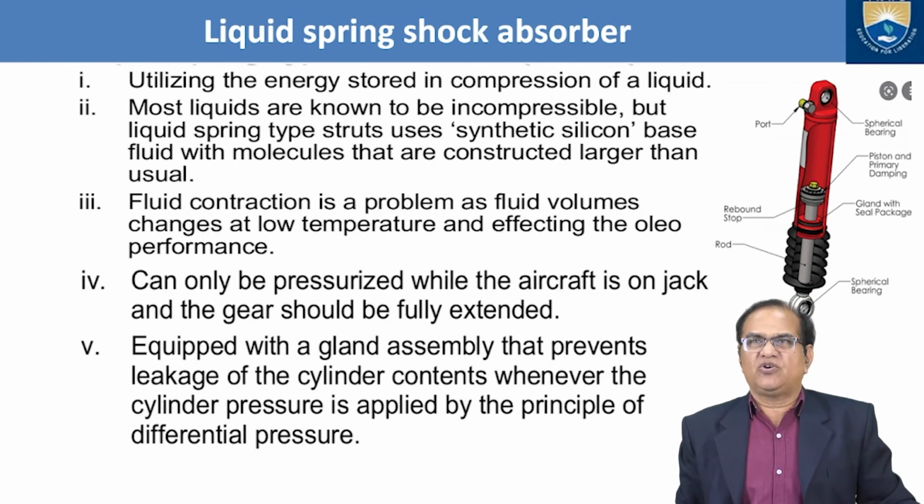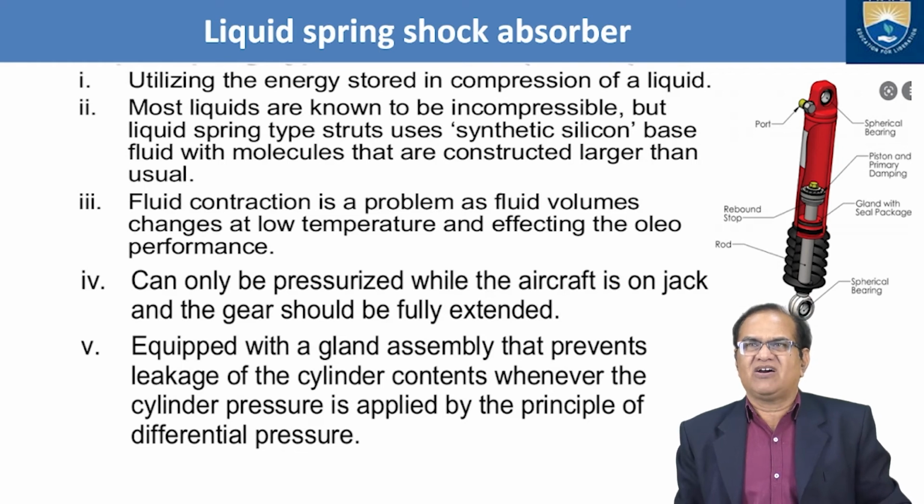Utilizes the energy stored in compression of a liquid. Most liquids are known to be incompressible, but the liquid spring type strut uses a synthetic silicone based fluid with molecules that are constructed larger than the usual.